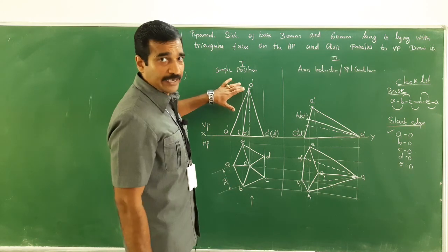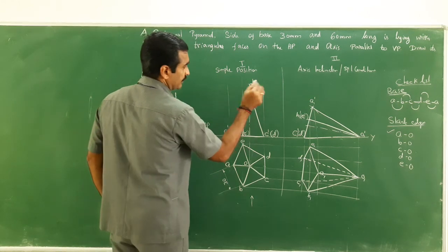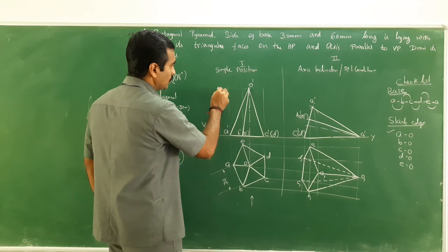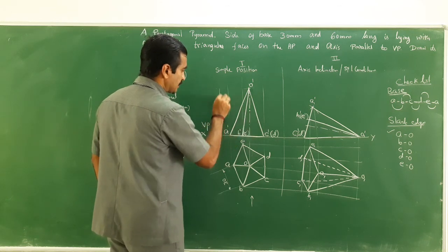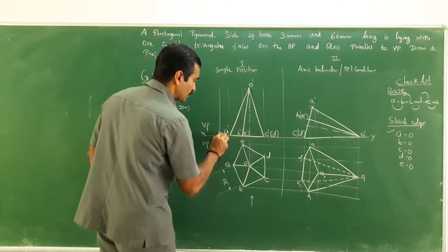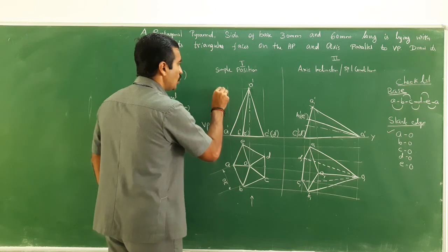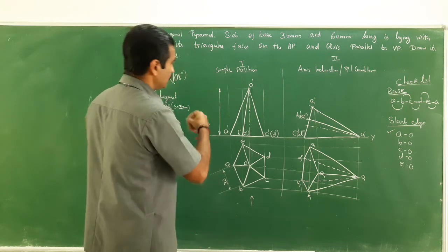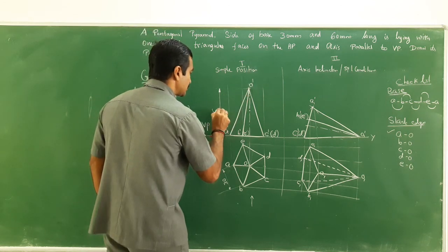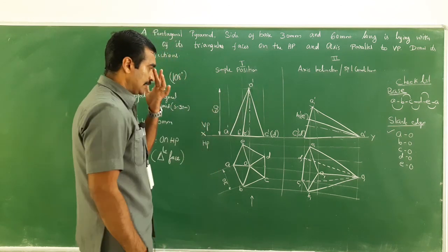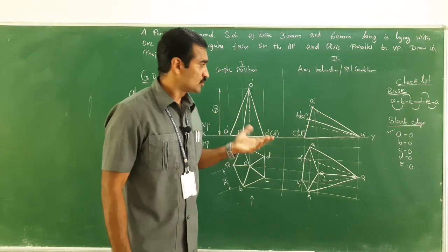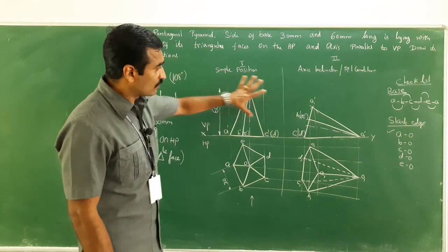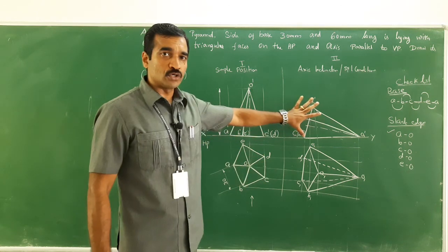Now the axis side needs to be mentioned. Draw a line parallel to the reference line. Now parallel to the axis, and over the dimension line, we will have to mention the dimension, that is 60 mm. Is there any axis inclination? No. So we need not specify it. Right. So with this, I have completed all the 4 drawings.